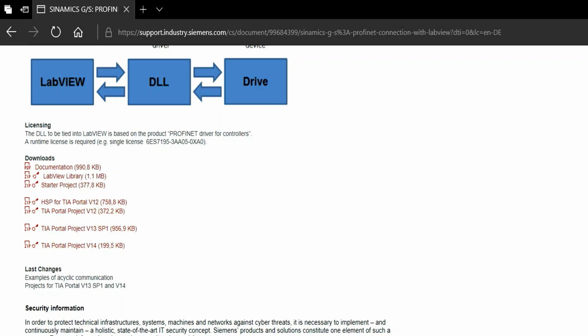In this software we need to configure the same topology project as in the Starter software, in order to compile an XML file used by LabVIEW to know what kind of hardware configuration and type of communication we will use to exchange information between the converter and the PC. All of the PROFINET input and output devices available in the hardware catalog of the TIA Portal can be incorporated.